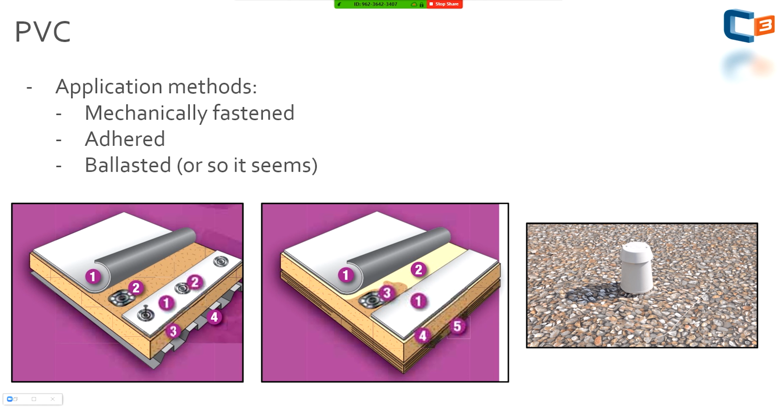And also, it's a good time to point out the vent on the right side that you see, they're vapor vents. And a lot of times that's an indicator that it's an overlay roof system, and you might have two roof layers. So even if you can't cut it at the time, if you're just walking it, it could just be something you note in your head. That's likely a second or even third roof layer.